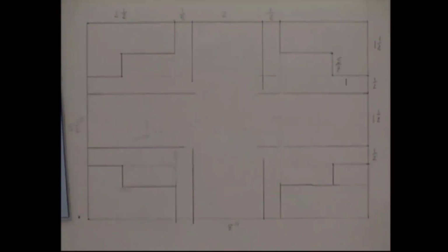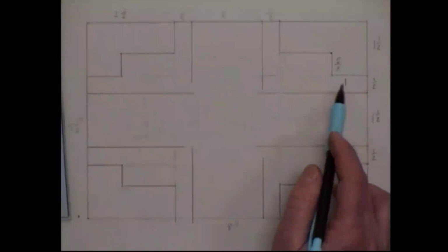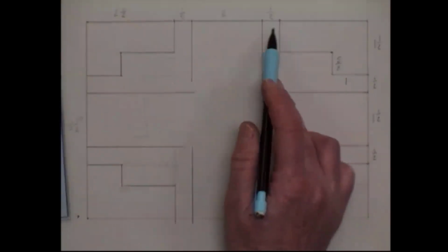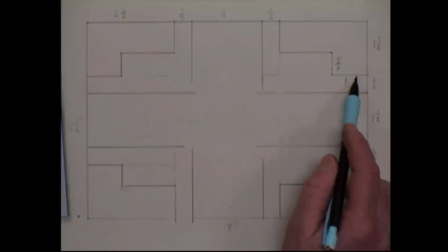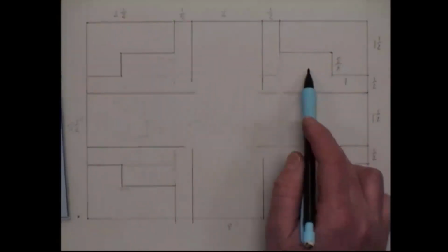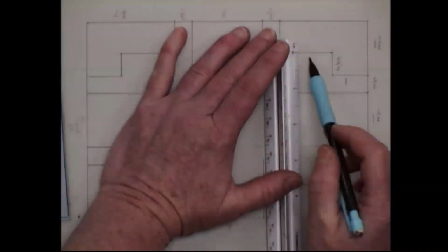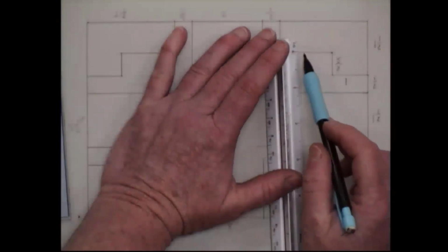Because I'm not given any additional dimensions other than what I've got on my paper already. So I'm working off of the dimensions I have to complete that inside structure. So I told you the key was that this 1/2 inch space is going to stay uniform all the way around. Well, we have it here and we have it here, but we still need to do a 1/2 inch here. So with our 16 scale, we'll just start in this corner that we started in originally.